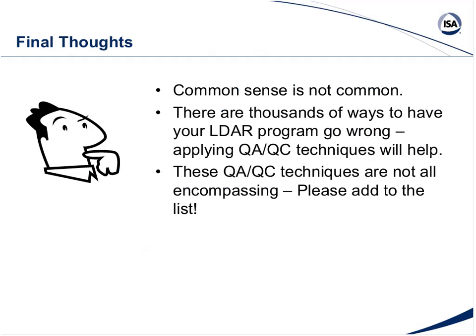LDAR is supposed to be a work practice that's supposed to be relied on with common sense. And we all know that common sense is not common. And it is truly something that's out there. When you walk out into the plant and you see a visual leak, you go, well, how come nobody reported it? And then you say, well, it's not time for the LDAR guy to come through. Well, it's still a visual leak, and I saw it, you saw it, so how come it hasn't been taken care of? And those are things that you have to deal with.